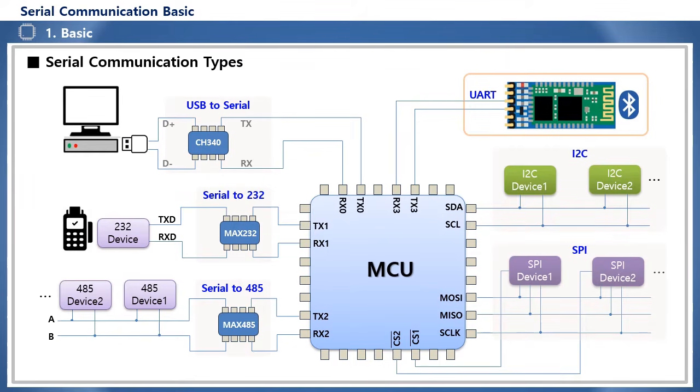It is mostly structured to be connected in a pattern on the PCB board, and only covers short-distance communication of less than 2 meters. MAX232, a serial to RS-232 converter, is a method that was developed to supplement the distance of less than 2 meters, which is the TTL-level MCU's own serial communication, UART method, and is a transceiver IC for applying RS-232 communication guaranteed up to 15 meters.